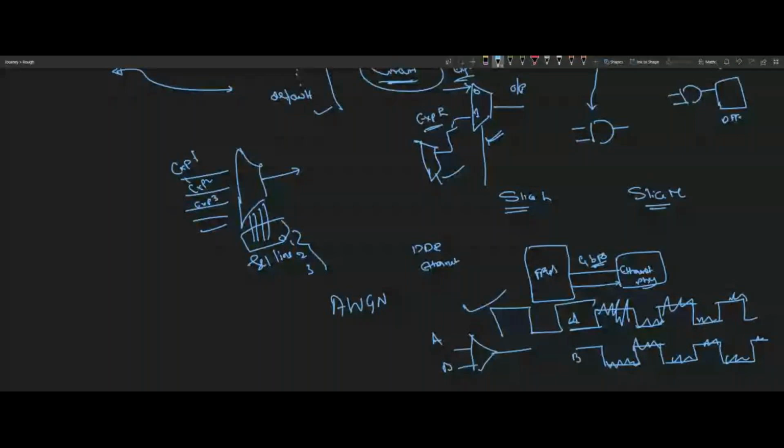So for example, now you have a Xilinx FPGA, you assume, okay, you have a Zed board. Let me consider a small design, you have designed one full adder. Now when you program that bit file of the full adder, your whole FPGA will act like a full adder, correct?